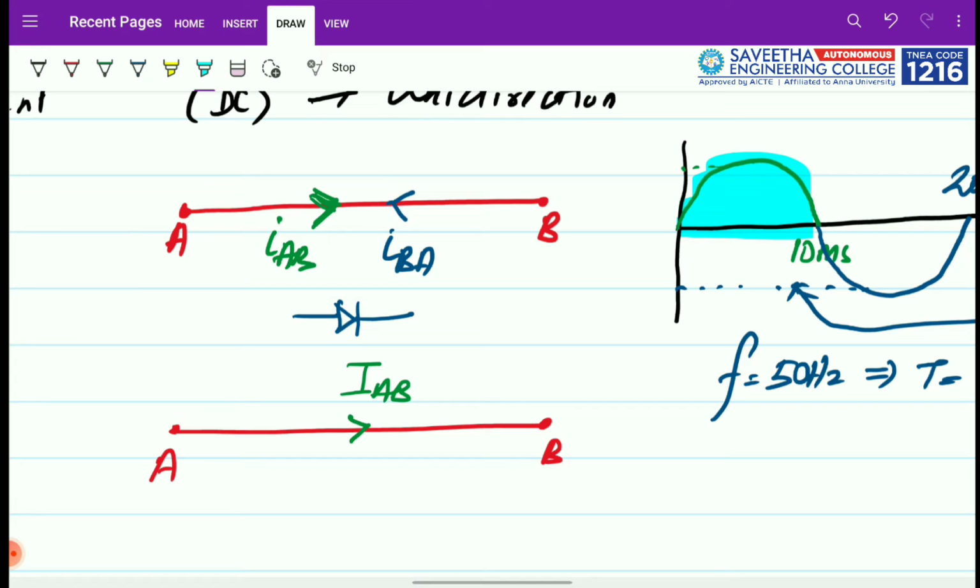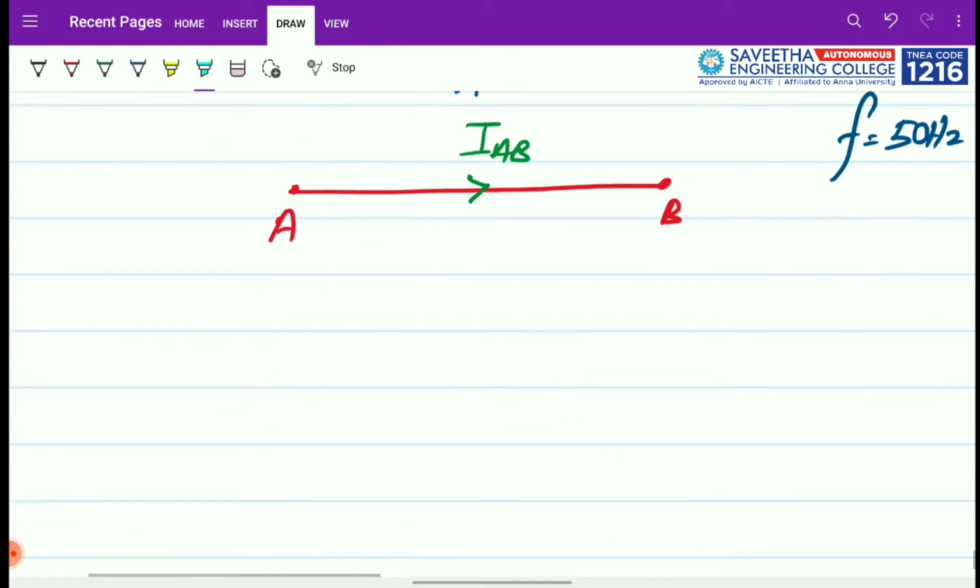So altogether, if you accumulate and see, all the waveform which is formed finally will be present in the positive direction, and whatever waveform in the input was on the negative side will not appear in the output. That means on the output you could see the waveform appearing in only one direction, which is the positive side. So eventually I can say that my diode is able to convert a bidirectional current to a unidirectional current. So this is how it started.